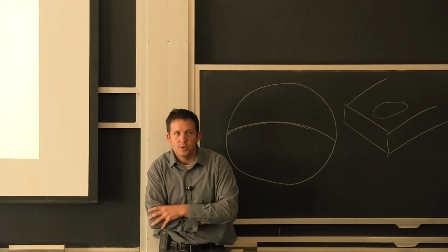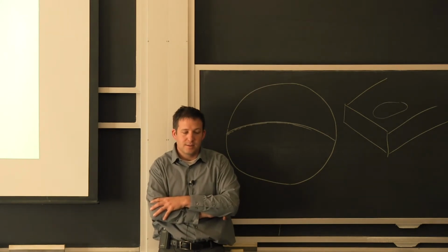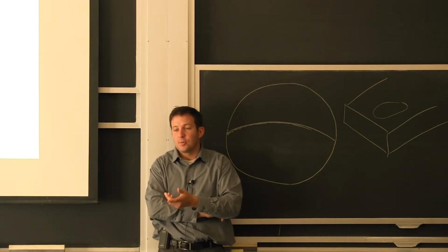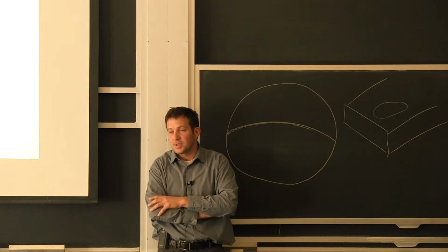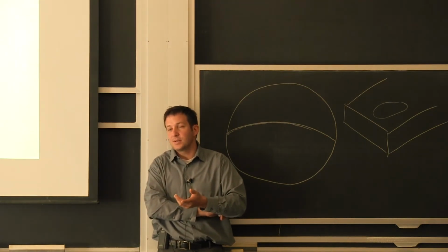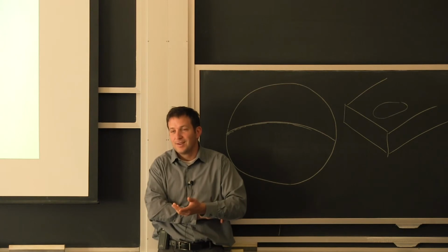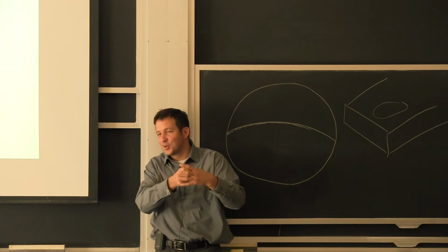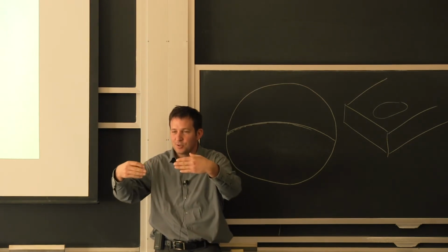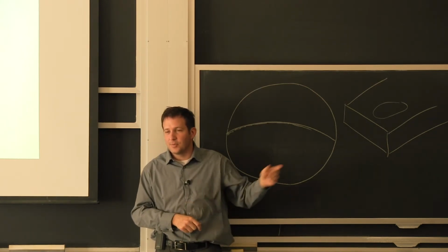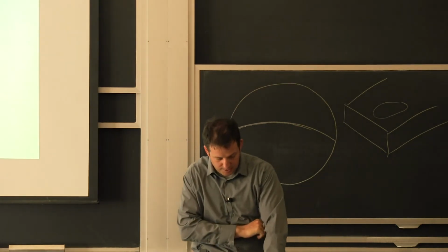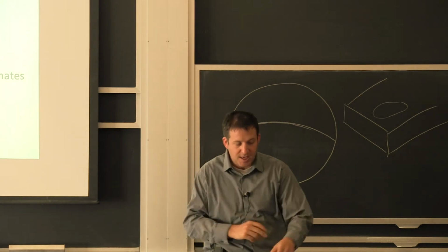And that's why in aluminum alloys, there are some special grades that have less iron, less impurities in general, that will increase that fatigue characteristic, if it's something that you care about. It could be that the problem is stress corrosion cracking, and it doesn't matter that you have a large particle somewhere. There's always going to be a crack, and it's a matter of making sure it doesn't grow by the failure of that protective oxide. So it becomes very specific, but I hope that you get the general idea.